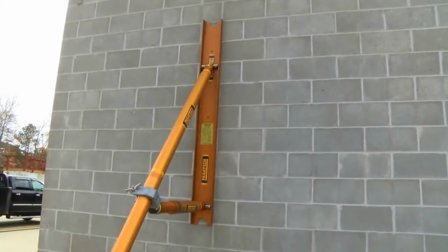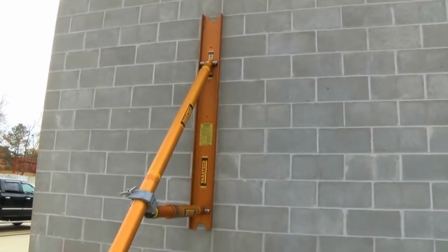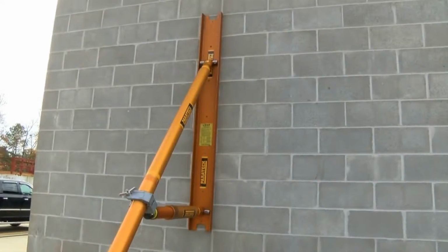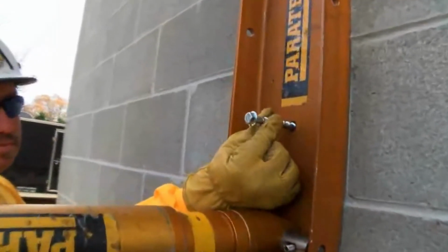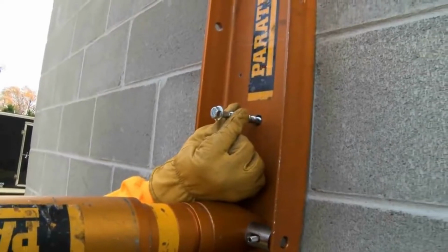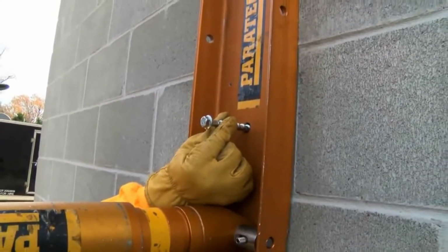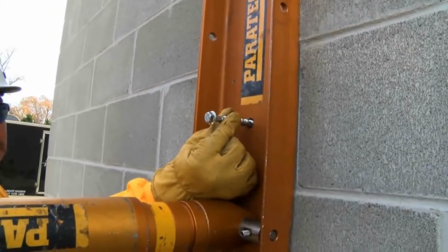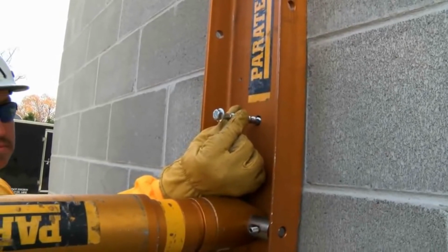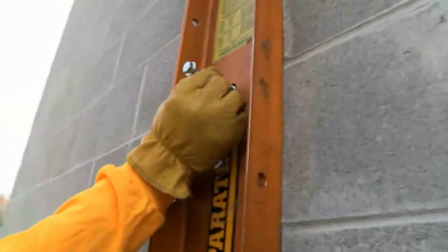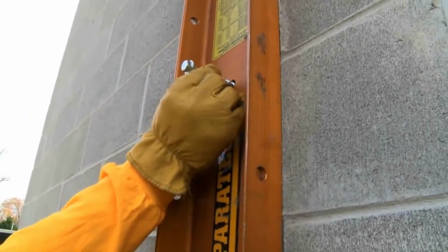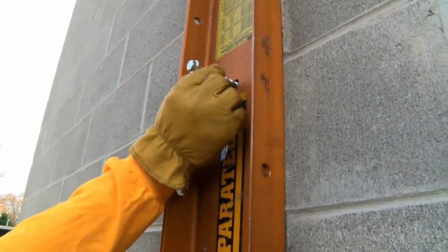Remember, the wall plate must be pinned to the wall in 2 places to prevent the raker system from sliding up the wall. There are 1/2-inch holes in the face of the wall plate to facilitate this. Since this is a block wall, we can use devices designed for this like Hilti anchor bolts or concrete screws. Using 2 bolts or pins will prevent the raker system from twisting. Put one down low on the wall plate. If they go up higher, put in a second one.